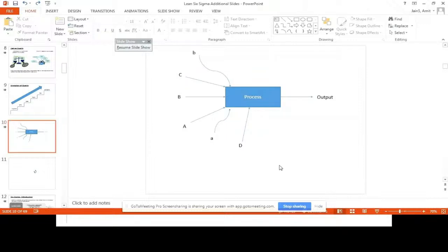Basically, through the usage of SPC, instead of looking at the process and trying to control it from gut feel, now data is getting used to get the feedback, and the control action is taking place basis the deviation from the expected output. And this deviation from the output is detected statistically by using SPC, also popularly known as control charts. And this entire process of identifying which factor to control, what is the variation, is called statistical process control.